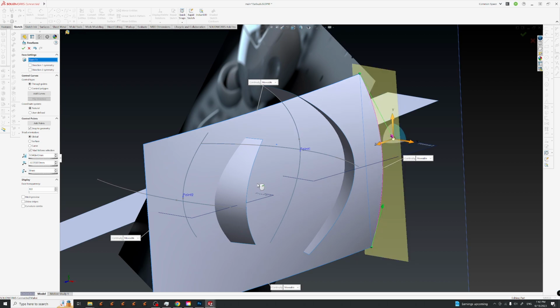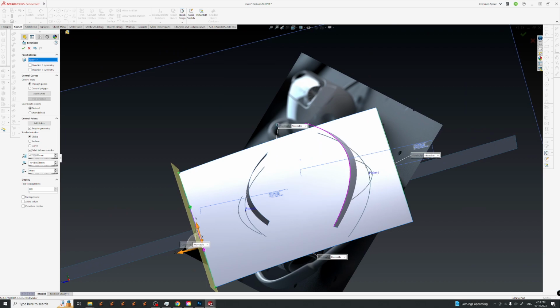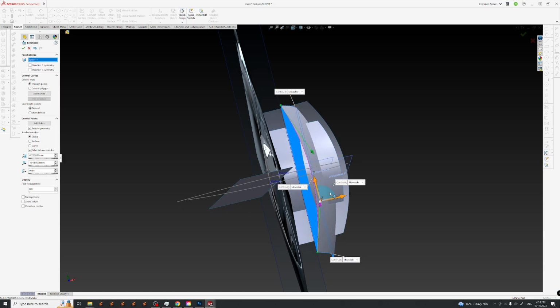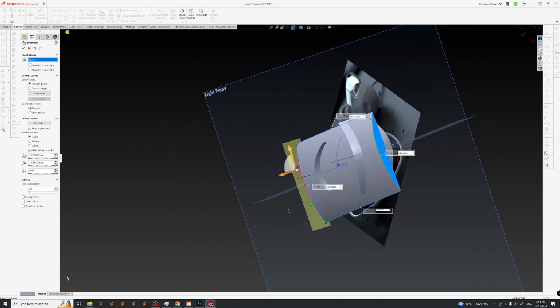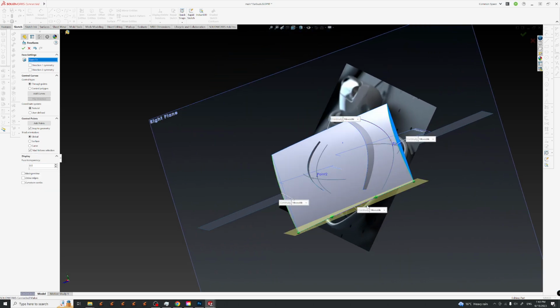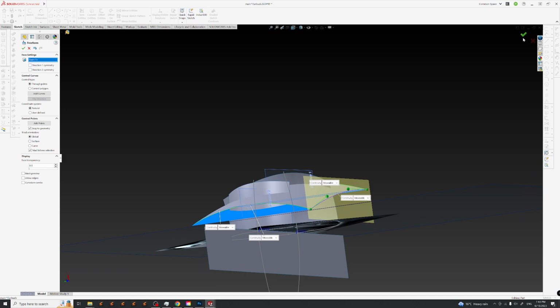We just need to make this surface curved, so let's move the tangents. You do not need to introduce any more lines in the middle. The more lines you have, the more you struggle to control the whole surface, which comes with experience. Once you start to understand the behavior, generally speaking, it's not only SolidWorks, it's almost any 3D design software, you will start to realize that less is better. So for now, I'm creating only this.